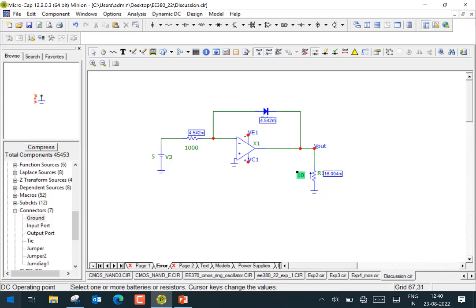So this can come from various sides. It could come from here because you're trying to pump in more current, or you're trying to draw more current from the load side. Either way, you're imposing a burden on the op-amp which is more than what it can bear. It has a current limit of a certain value that you have to obey. So that's the message of this particular one.